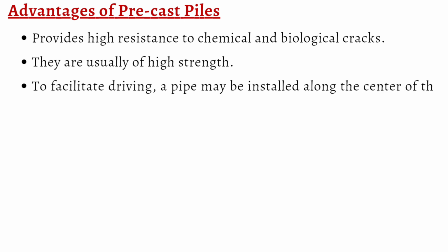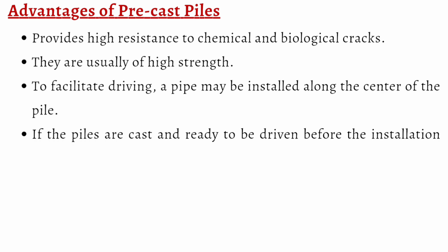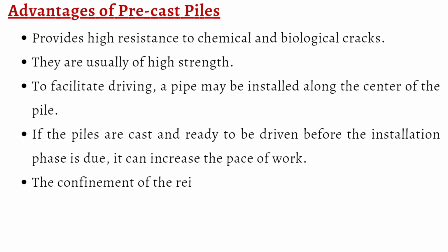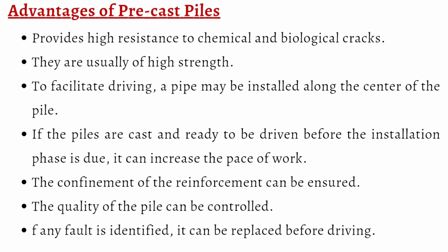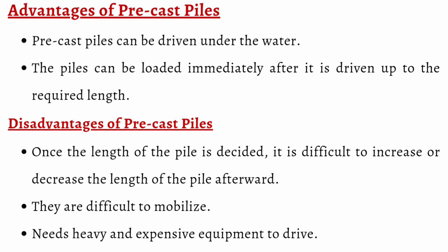Concrete piles. Precast concrete pile. The precast concrete pile foundation is cast in a pile bed in horizontal form if they are rectangular in shape. Usually, the circular piles are cast in vertical forms. Precast piles are usually reinforced with steel to prevent breakage during their mobilization from the casting bed to the location of the foundation. After the piles are cast, curing has to be performed as per specification. Generally, the curing period for precast piles is 21 to 28 days.